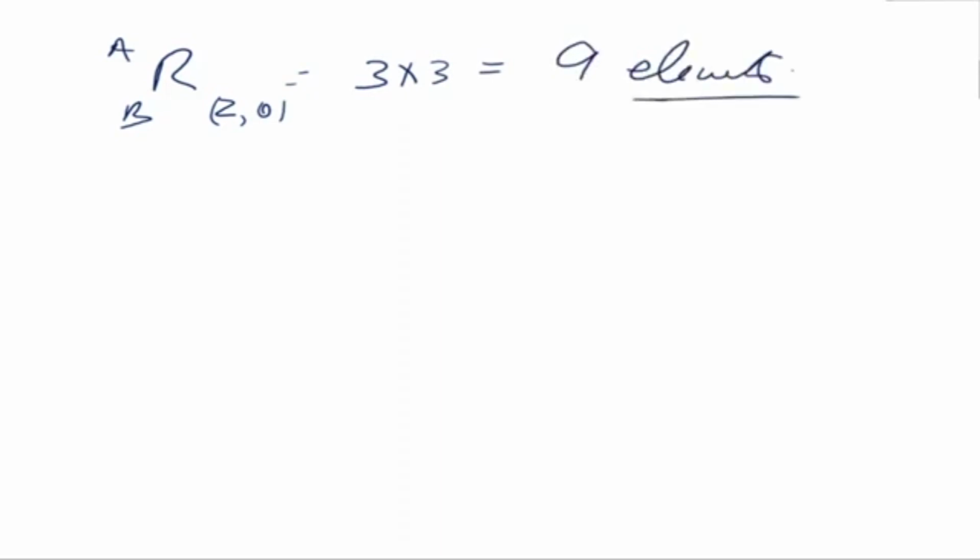So this basically means that your rotation matrix R A to B, Z theta, is 3 by 3, which means it is 9 elements. But you do not need 9 elements to represent the rotation of a body in space. This is interesting. Why? Because you have 6 constraints, which means that those 9 elements are not all independent of each other.